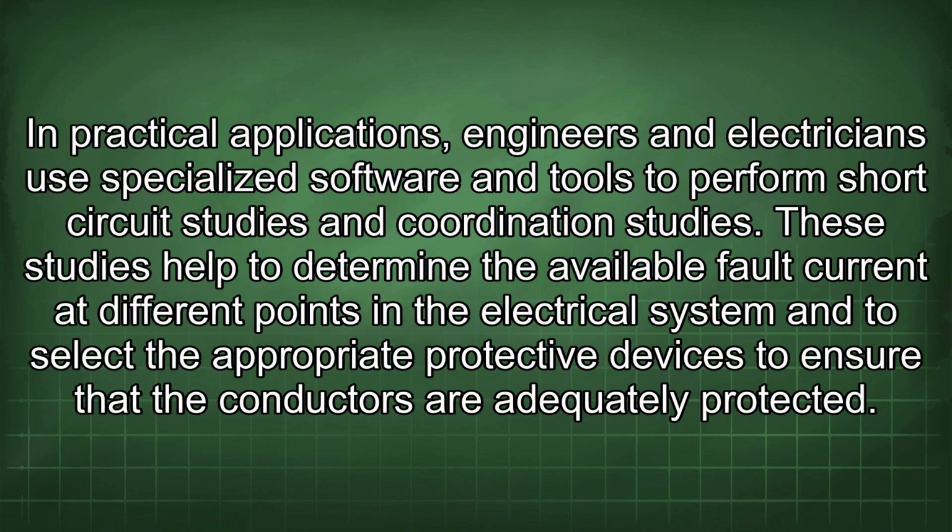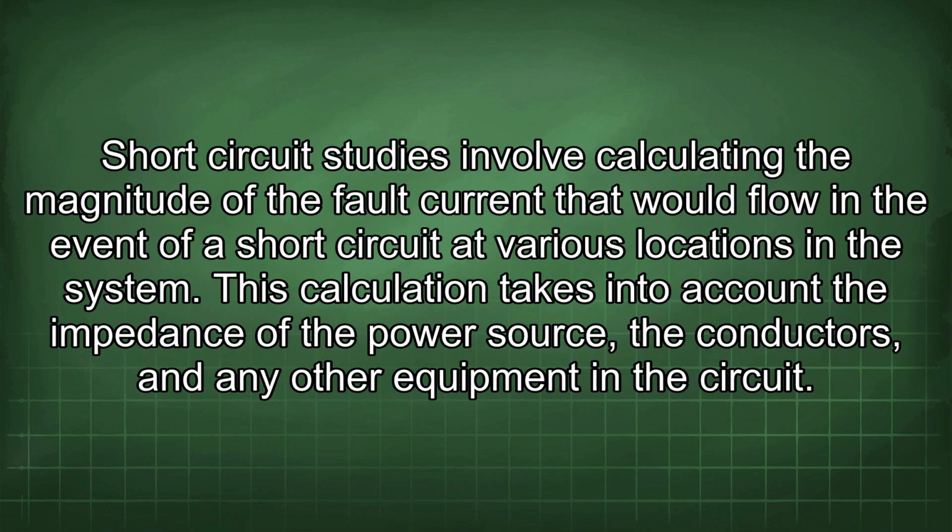In practical applications, engineers and electricians use specialized software and tools to perform short-circuit studies and coordination studies. These studies help to determine the available fault current at different points in the electrical system and to select the appropriate protective devices to ensure that the conductors are adequately protected. Short-circuit studies involve calculating the magnitude of the fault current that would flow in the event of a short circuit at various locations in the system. This calculation takes into account the impedance of the power source, the conductors, and any other equipment in the circuit.